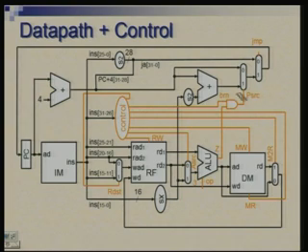If the instruction is not a branch instruction, you will have a 0 here, which means that P source is 0 irrespective of what is Z, and the multiplexer passes the upper input. So, when it is not a branch instruction, we do not branch, we do not even look at Z. When it is a branch instruction, we will have this as 1. Controller will make this output as 1.